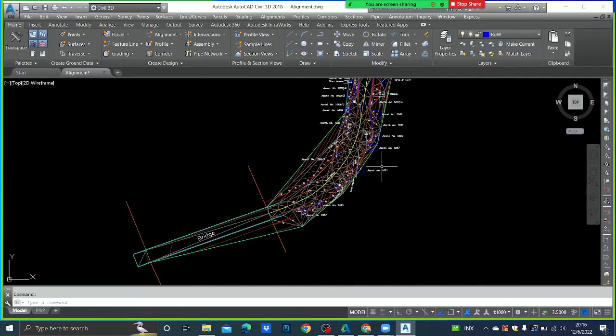So what is the normal speed of an expressway in Sri Lanka? Usually we go from 100 kmph to 120 kmph. For such higher speeds, you have to have spirals. Otherwise, the driver cannot get his proper spiral curve. That is why we use spirals, right? Okay, then